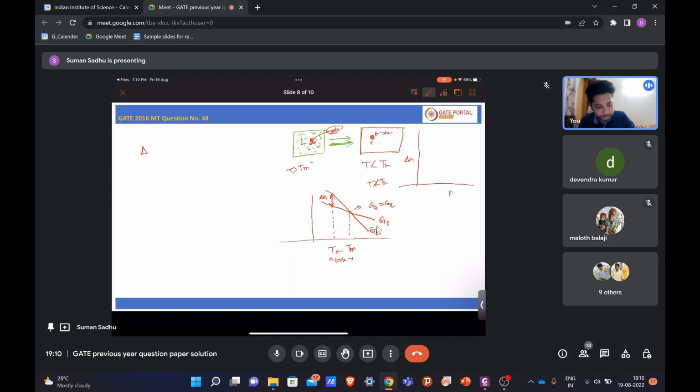But when you are forming a solid, what is happening? One interface is also forming, right? A new interface. Earlier it was totally liquid, but when you are forming solid, it is liquid here but solid here. So this interface is forming, right? To form a new interface, you will need some kind of energy, right? So when you don't have any driving force, at this temperature you cannot form the solid. So you have to decrease the temperature a bit, so that you have sufficient driving force or sufficient energy to form this nucleus.